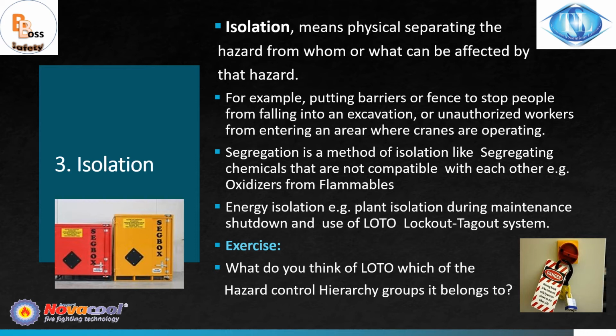Okay, maybe not very famous, but it's a big accident where a warehouse that was used for storing hazardous chemicals, both the storekeeper and unfortunately the safety officer didn't know how to read the labels. So they stored flammable material with oxidizers because both of them show a flame. They didn't know they are incompatible.